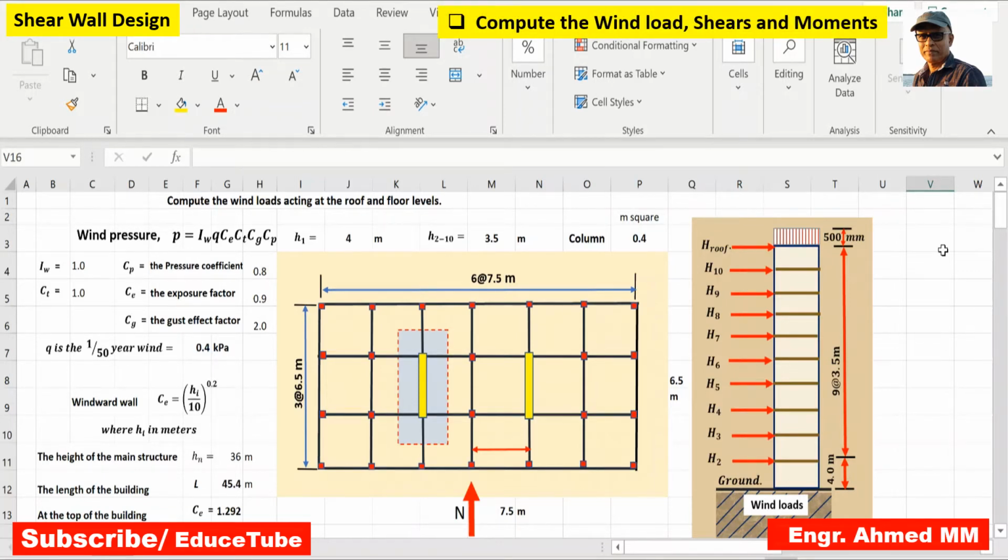In the Excel sheet, I am going to calculate the wind loads acting at the roof and floor levels. To do that, I will use the wind pressure formula. Already I explained all the factors used in this formula. Regarding the exposure factor value, I already explained that this value will be greater than or equal to 0.9.